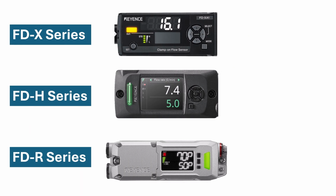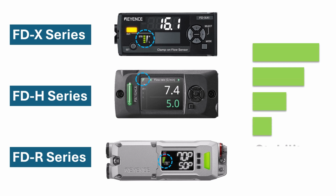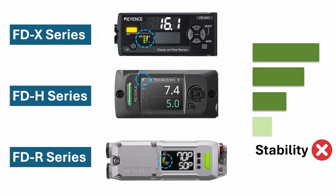This can be easily identified on our flow meters with what we call stability bars. Each of our flow meters has 4 stability bars, and with 1 bar blinking, that indicates no stability, and with 4 solid green bars illuminated, that indicates full stability.